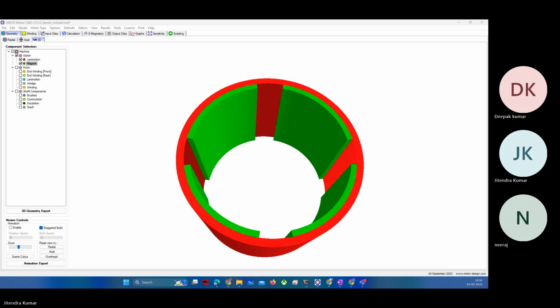Sir, how will it demagnetize permanently by the temperature? By the temperature, and that temperature will be generated from the armature current. If you are creating a demagnetizing component of armature MMF from the armature winding, and it becomes higher than the tolerance point of the permanent magnet, then it can be demagnetized. Okay, sir. It will permanently demagnetize. Yeah, so then it will be of no use.